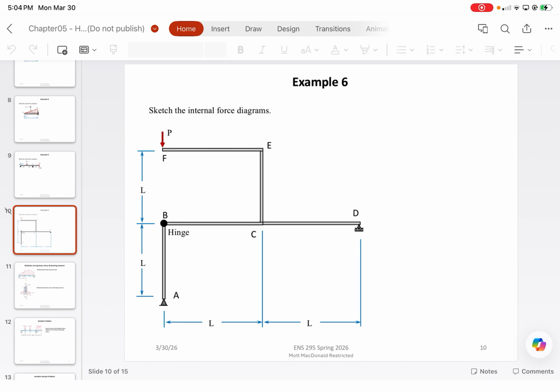Until you get to the point at the very bottom right here, which is full yielding, which is what you were talking about with the area of the top having to equal the area of the bottom. The reason for that is that when you sum the forces, they break down to stress times area, but the stresses have to equal each other. Because of that, the areas have to equal each other. Okay. So that's where it mathematically comes from. If you were able to get that and work on it in the homework, awesome. That's extra credit. But if not, I'm not going to grade your homeworks based on that.